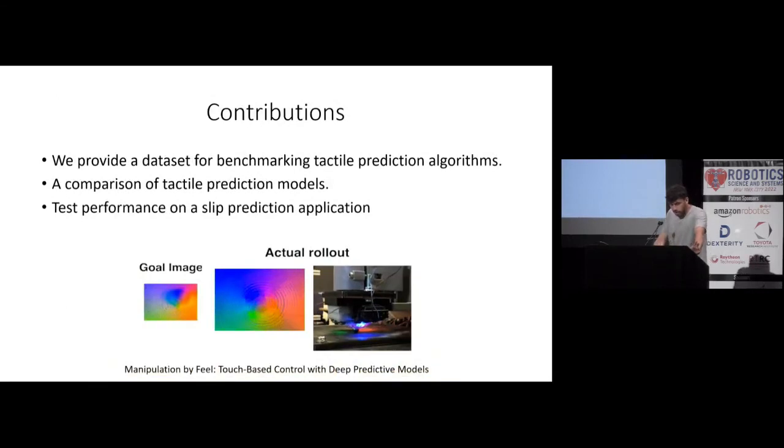And although some researchers attempted to perform tactile prediction before, these projects were very application focused and they didn't provide us with any insight into the tactile prediction problem itself, only in how to use it afterwards. So in our work, we did a comparison study between different unsupervised learning models applied to pick and move motions, and we further explored prediction models within the context of a slippage prediction application, where we try to work out if and when slippage will occur during a pick and move task.